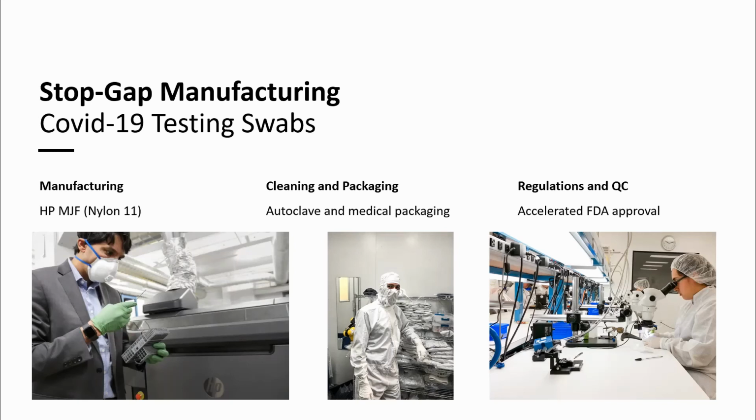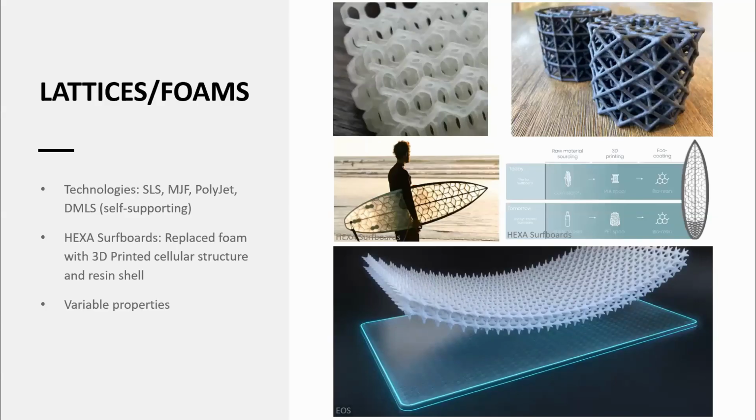Using the additive technology from beginning of design to production was only a 35-day cycle. For manufacturing, we produced swabs using MJF nylon 11, and we were also able to achieve FDA approval and high QC standards for these parts, as well as securing sanitizing and medical packaging.